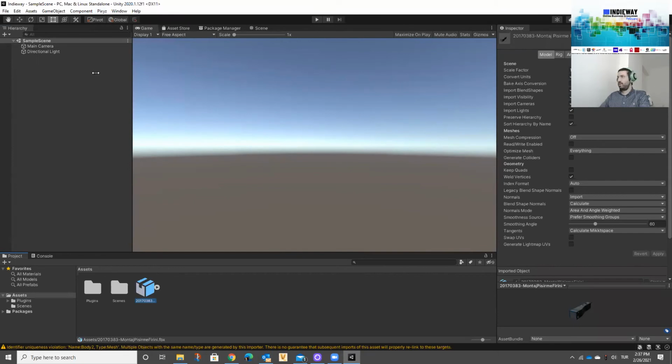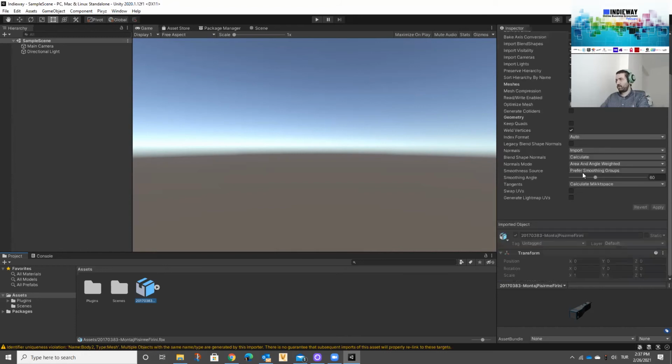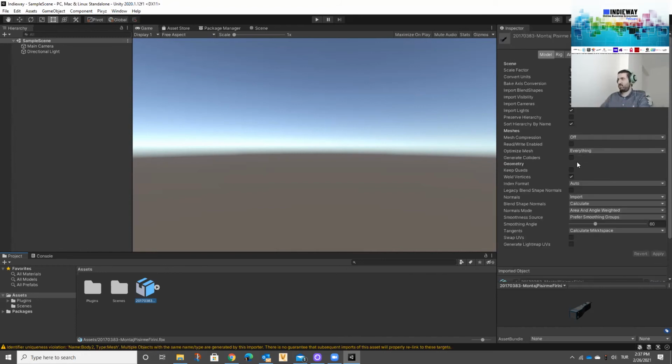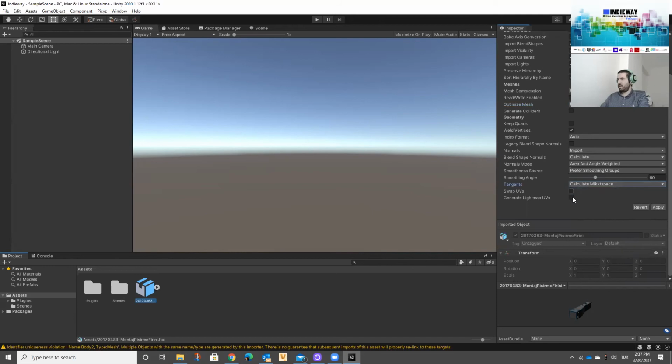Look here, first, My first FBX. What was it? I picked a different FBX here, and in CAD programs, the scale factor is important. Different measurement units may be used by different programs, so you must be careful about it. As I explained, solid components in CAD are in centimeters, while in Max or Unity it's meters, so it may look different. You change this here. I will not do any optimization here because the units are compliant.